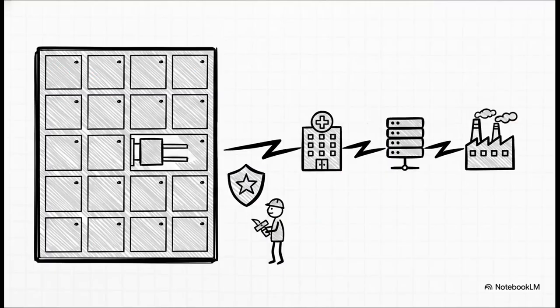But honestly, the sheer power isn't even the most crucial point here. It's the architecture. Switchgear is defined by strict compartmentalization. It features draw-out functionality, which means a breaker can mechanically move through connected, test, disconnected, and removed positions. This is all about ultimate safety and zero downtime. It means you can physically isolate, remove, and swap out a single massive breaker, while the rest of the hospital or data center stays totally online. Throw in tested arc-resistant options, and it makes total sense why switchgear is absolutely mandatory for mission-critical facilities.